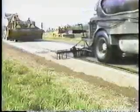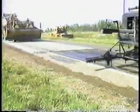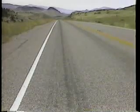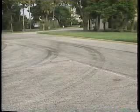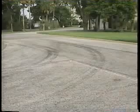Uneven coverage shows up as streaks on the surface. Too much oil in some places, not enough in others. The chips will strip from lean or thin areas, while the oil will bleed in fat or heavy areas. Bleeding creates slippery spots on the surface, a safety hazard.